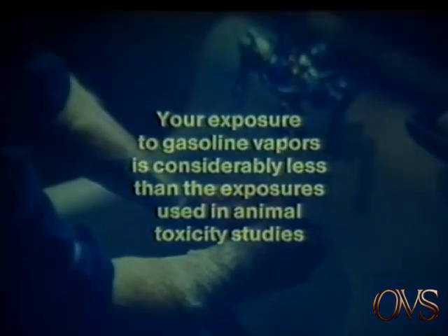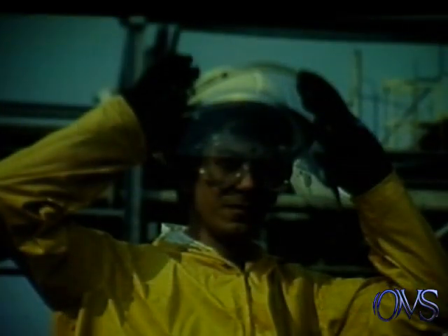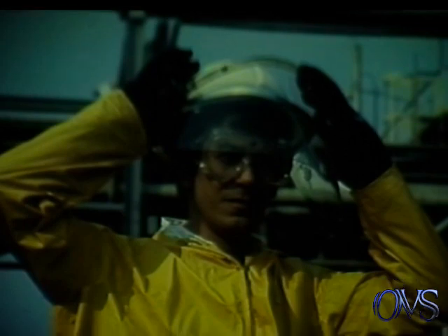First of all, personal hygiene is a must. If your hands get covered with gasoline, wash them as soon as possible with soap and water. Should you splash gasoline in your eyes, rinse your eyes with water, and if irritation persists, seek medical attention. Gasoline vapors in sufficient quantity to make you dizzy would also be highly flammable. Wear protective equipment, including goggles and rubber gloves, where contact with gasoline is possible, and test for flammable vapors.